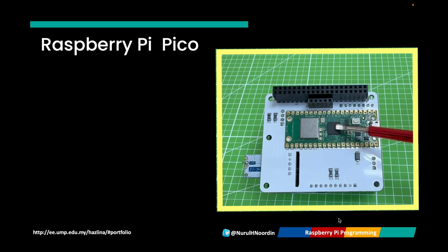It has ultra-low power consumption, which is ideal for battery-powered projects. The Raspberry Pi Pico has 40 pins, including 26 multifunction GPIO pins, enabling direct interactions with components like LEDs and motors, temperature, motion, and light sensors, and communication modules like I2C, SPI, and UART. Unlike the Raspberry Pi 4, which runs on Linux, the Raspberry Pi Pico is programmed directly via MicroPython, or C or C++, making it simpler and more efficient for embedded applications.